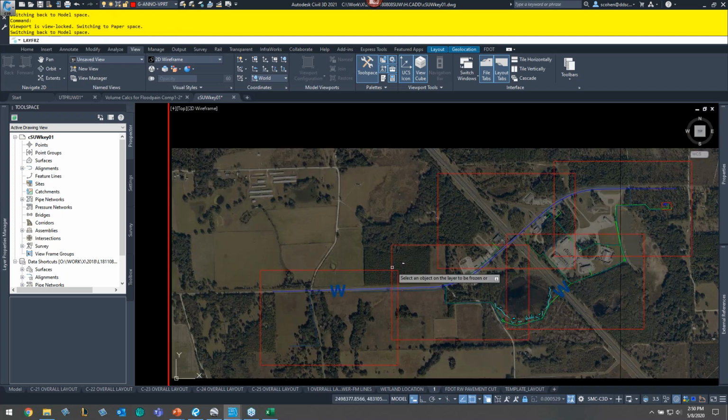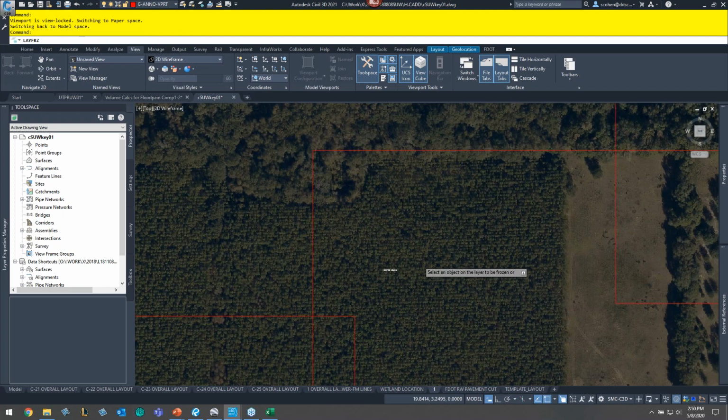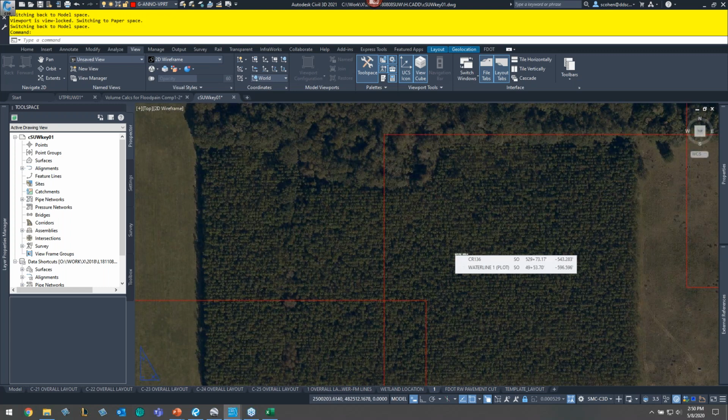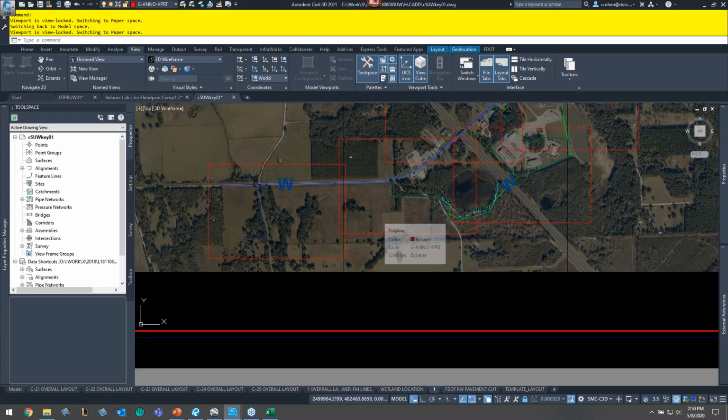And what is this right here? That is some text. So actually, that's probably on layer 0. I'd have to go into that. I'm not going to worry about that, but I'd go into that reference file. That's why you should never put anything on layer 0, for those of you that don't know that, except for stuff for blocks. All right. So now I've done that.